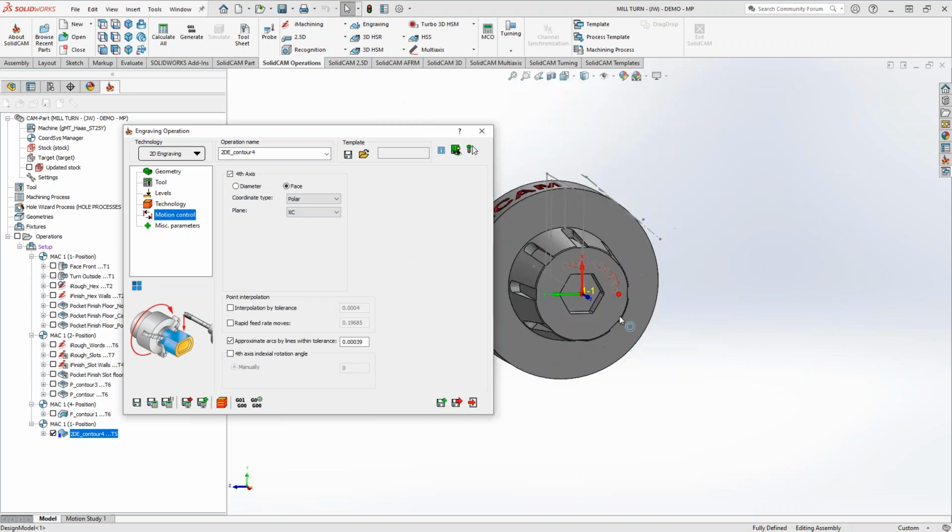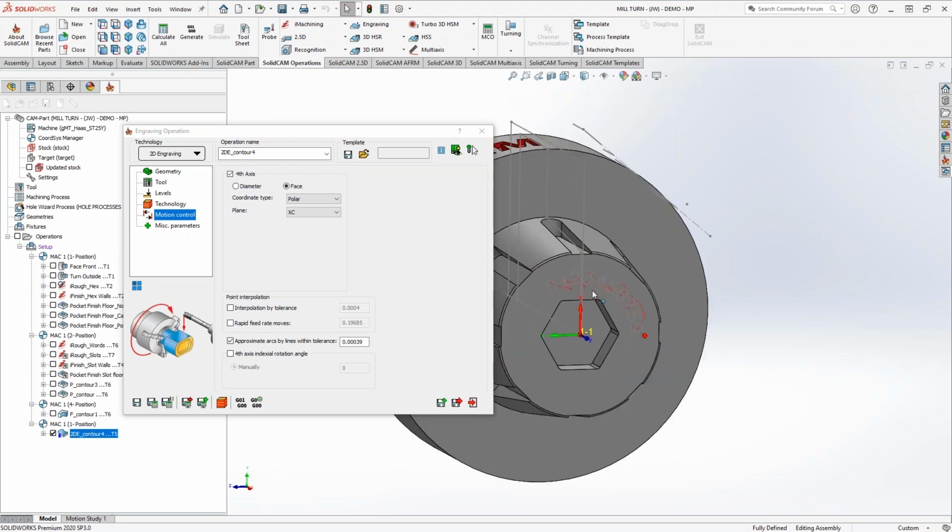If you had a feature that is not necessarily simultaneously moving, but it literally is just over out here too far away in Y, this option right here, a lot of people don't see this one. This is to manually index the part. So I can program it with a simple pocketing toolpath or a simple engraving toolpath or whatever it is, but I don't actually have the ability to take the tool over here to do that.